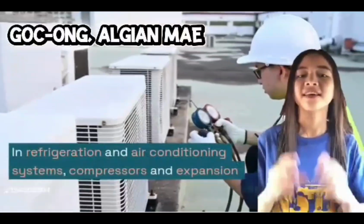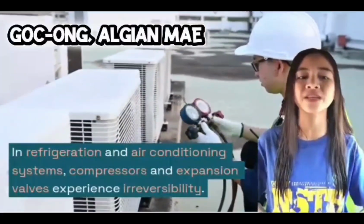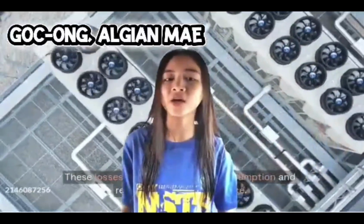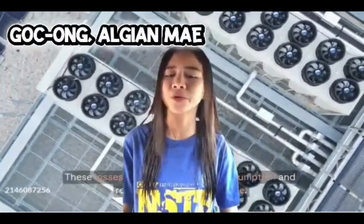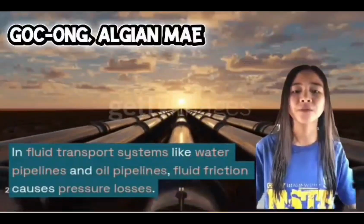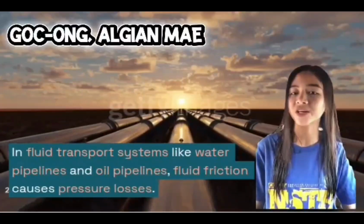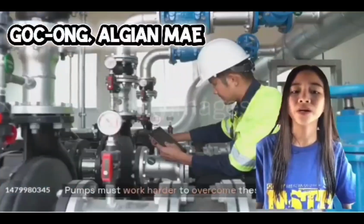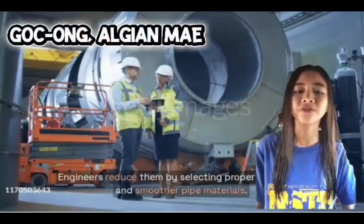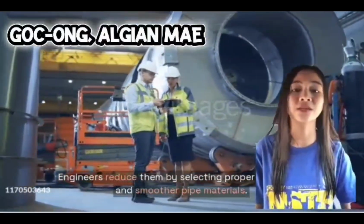In refrigeration and air conditioning systems, compressors and expansion valves experience losses. In water pipelines and oil pipelines, fluid friction causes pressure losses. Pumps must work harder to overcome these losses. Engineers reduce them by optimizing pipe size and using smoother pipe materials.